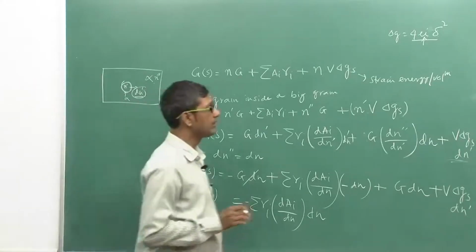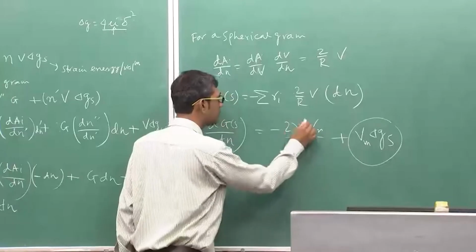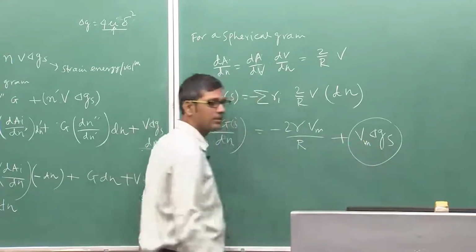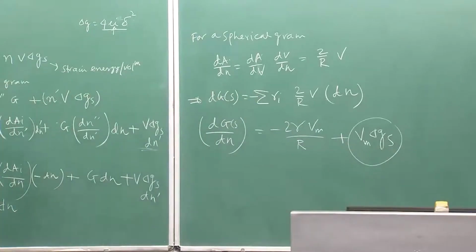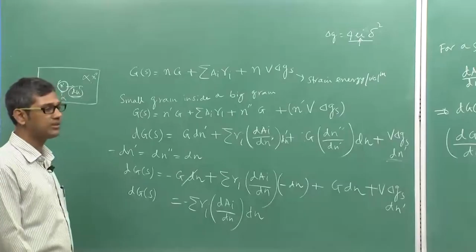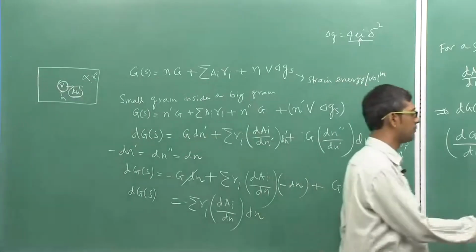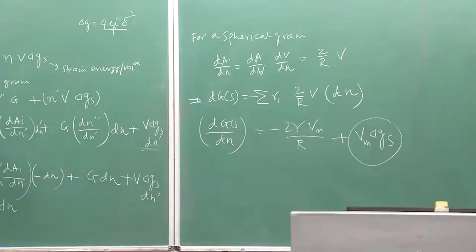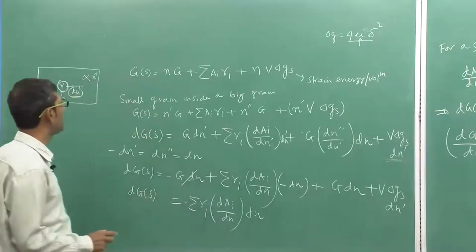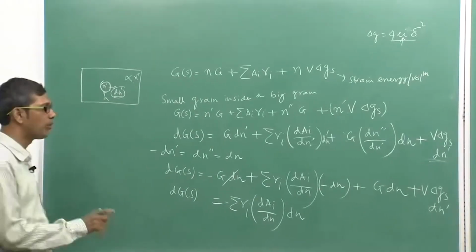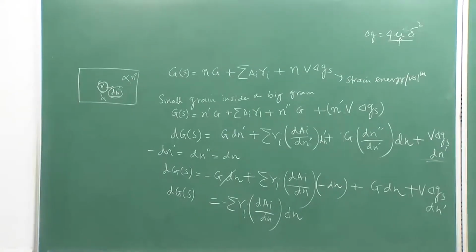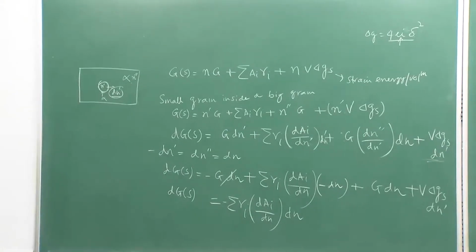So, in actual reality, we have to consider both the effect of the surface energy of the interface plus the strain which is generated because of incoherency or semi-coherency or coherency, whatever the situation. All will lead to some kind of strain, but the value of the strain will vary depending on the type of interface you create. So, this is exactly what I wanted to tell you: by simple thermodynamic analysis, even free energy analysis, one can show that different kinds of situations are mathematically or theoretically possible.